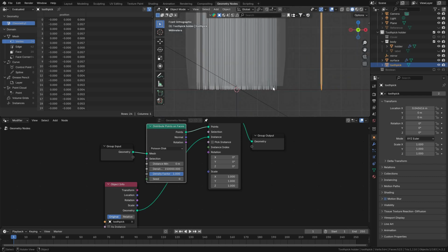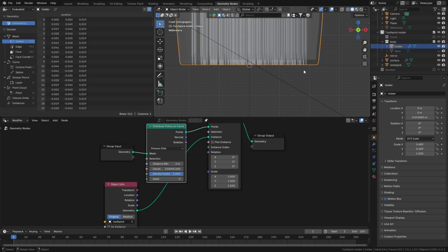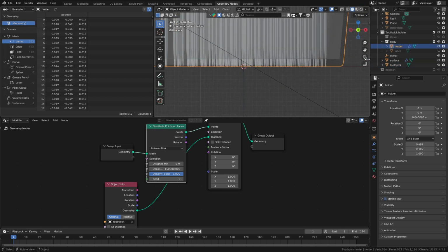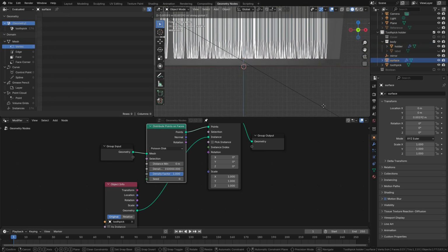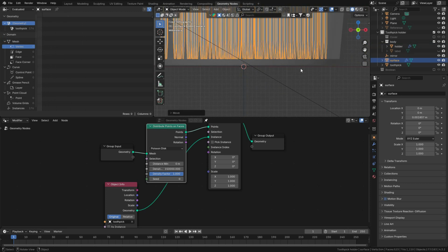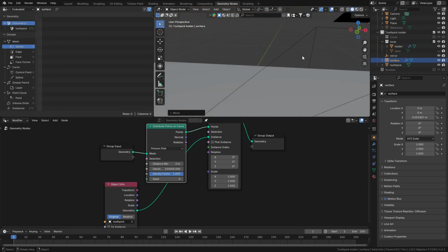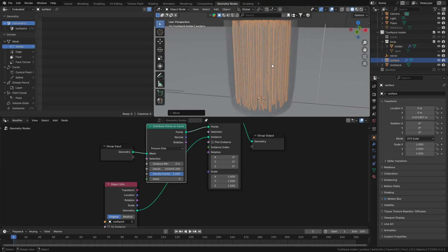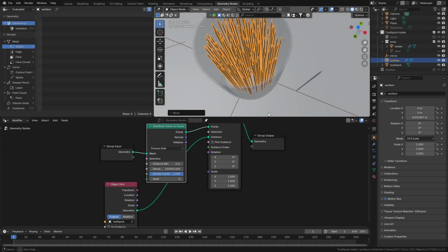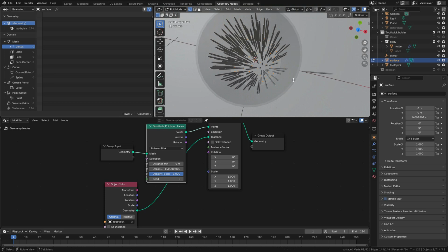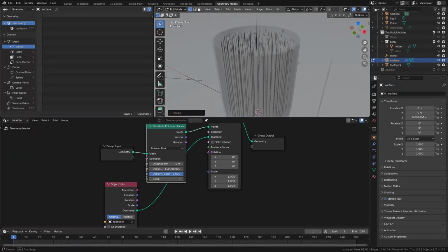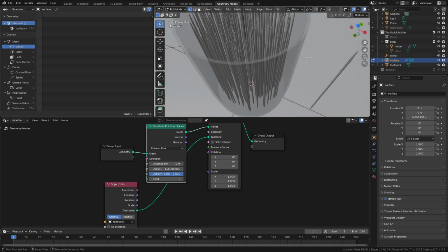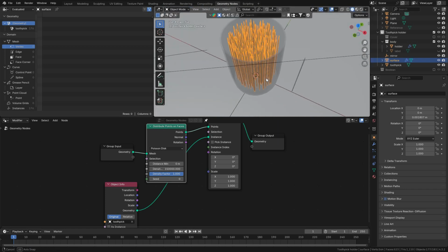We see our toothpicks when we come to front view. It is unrealistic, so we'll select them. That is our surface. Press G, then Z, holding shift, then bring them up ever so slightly, just so that they touch the surface, and this is fine. Feel free to edit the mesh any way you want to. Just make sure that, okay, go back to object mode.